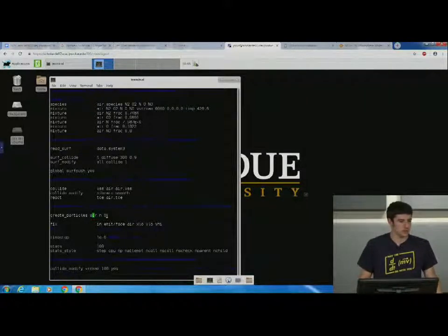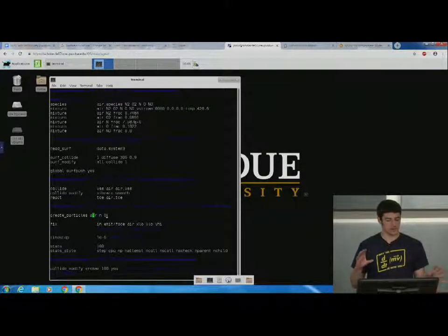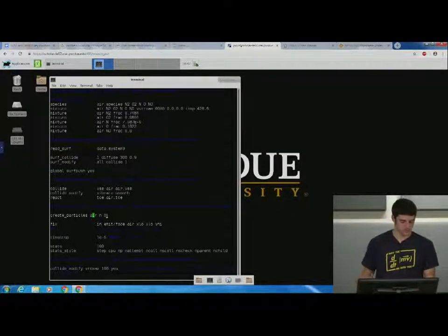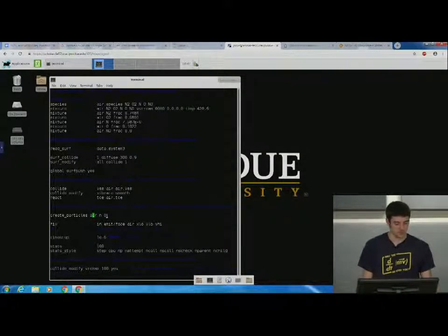Well, that depends on your flow from there. But this is just starting off, and it's not going to start off with anything realistic. It samples all the particles for their locations and the internal velocities and temperatures according to the distribution function. Certainly in this case, a reentry flow, those will be way off. It'll be much colder to start, so I need to give it some time to form a more realistic solution. But I generally like to just put this in to get started.